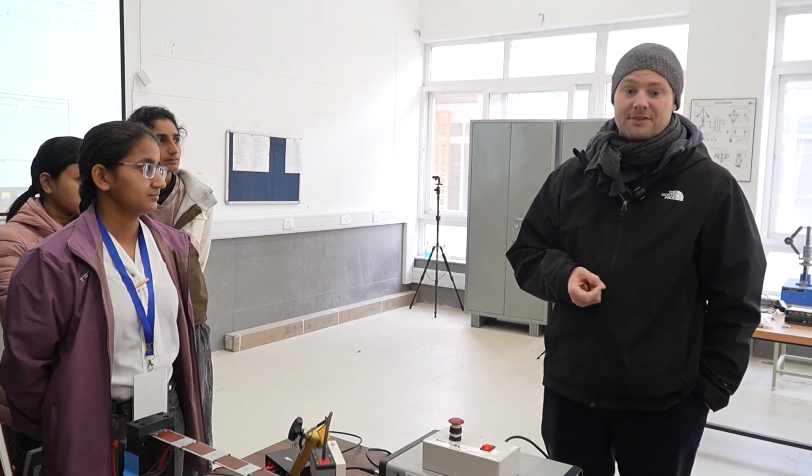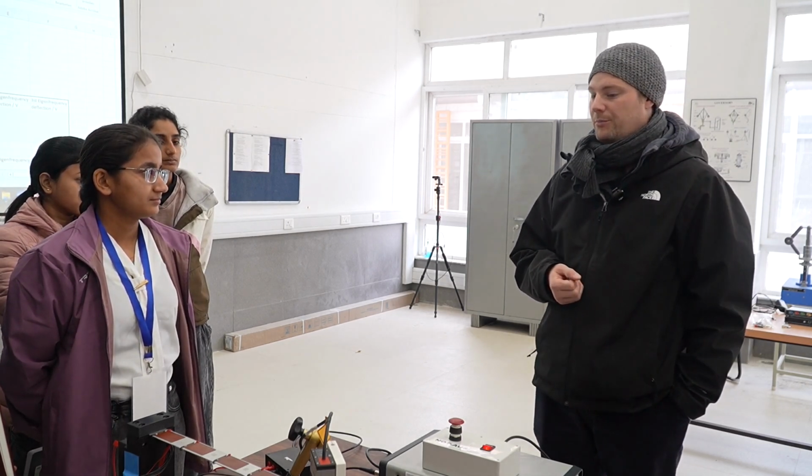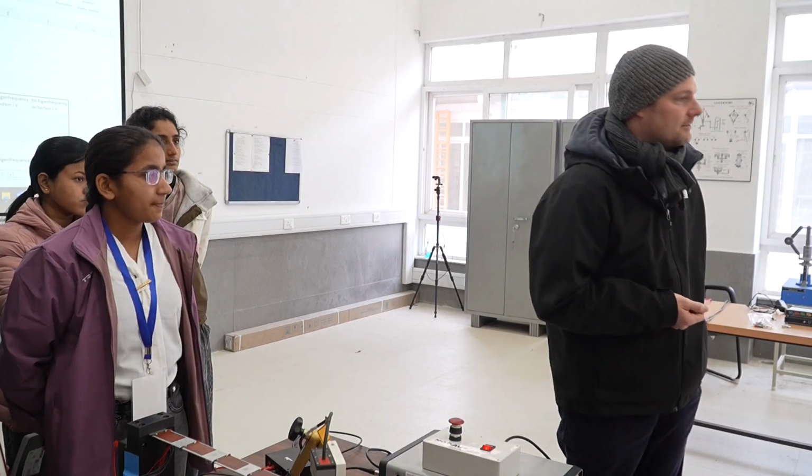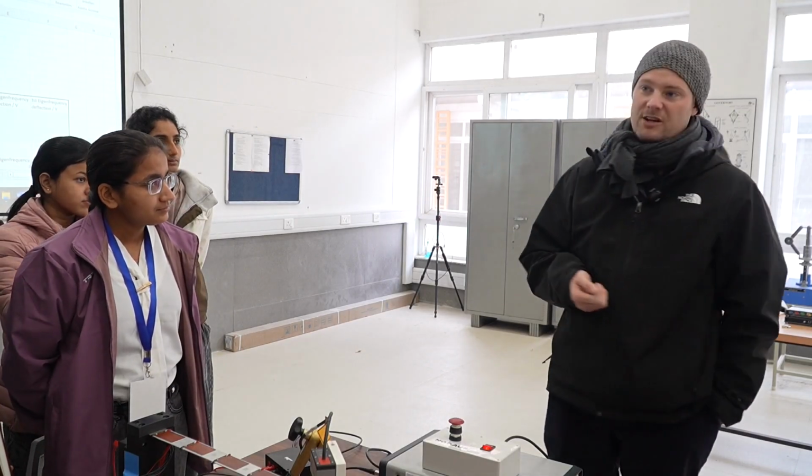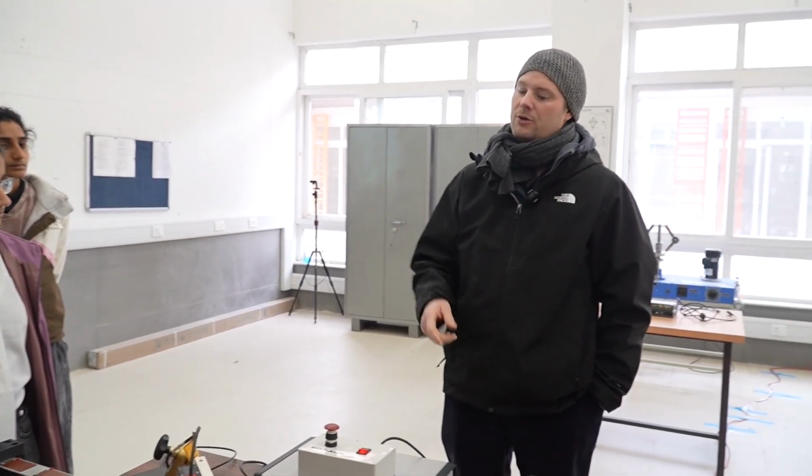So this is what we can do, but more precise, and I think still until today, for a modal analysis of an aircraft you would really do a single frequency excitation. And this you do by using a sine, so a harmonic signal, and then you slowly increase the frequency, and you look at what happens in the experiment. So this is what we will do now.